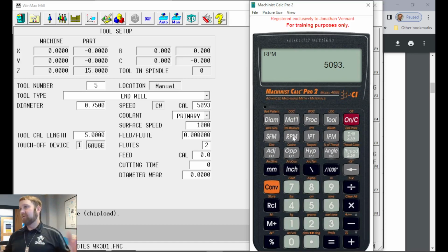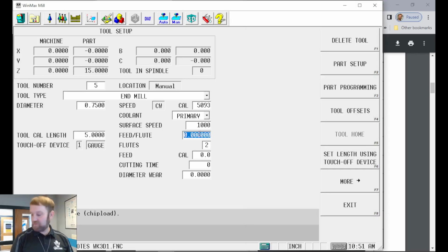It's the same formula when we do our tool library in Mastercam. The same thing's going to happen there. It's calculating it for us. These aren't VU formulas. These are industry standard formulas that the software uses, the calculator uses, the CAM system uses. Okay, it's the same formulas. Feed per flute for that 3/4 is 6.5 thou. It's got 3 flutes, so we feed it at 99 inches a minute.